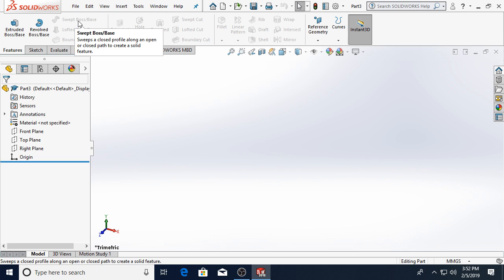So I'm from the thermal fluids field, and we use that a lot in duct geometry. For example, these diffusers up here in the ceiling have a circle at the top of the diffuser, but the output of the diffuser needs to interface with the suspended tile system, and so it has to be square. We also use that in intake and exhaust. You may want an intake profile that isn't circular, but you want your duct to be circular to minimize drag